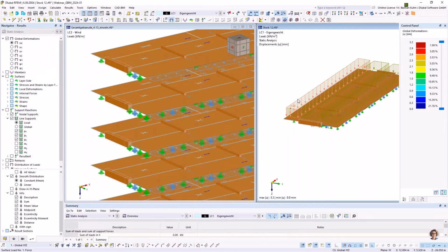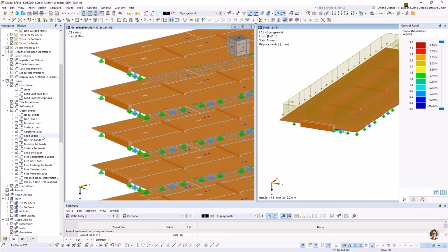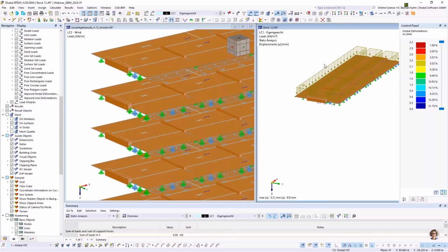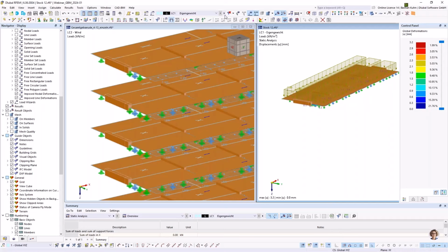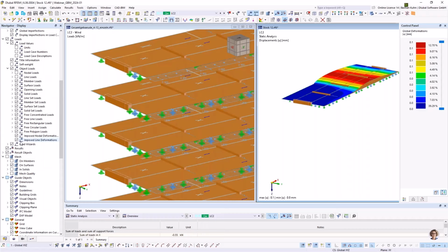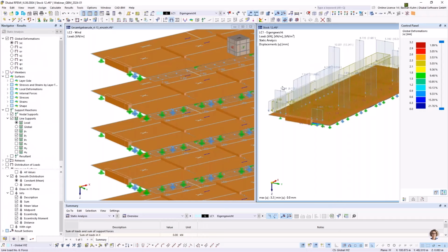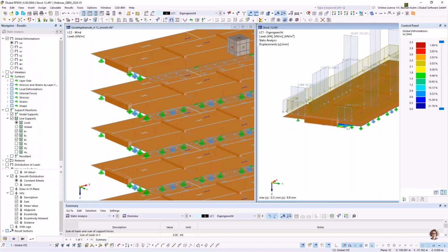And when you calculate this one here, do I have results? Oh, I have results. Here, and then hold on, switch off. Also in this model here in story 12, I have self-weight and also horizontal force. Hold on, line loads. So you see they are here. And now when I look for load case 1, you see that I have here a value of 5.6, which is pretty much near what we have in the bigger 3D model.